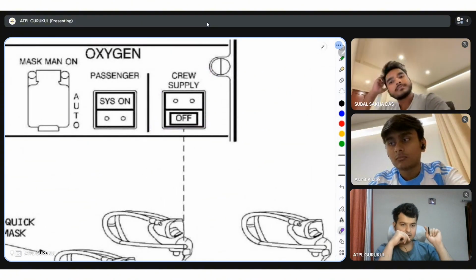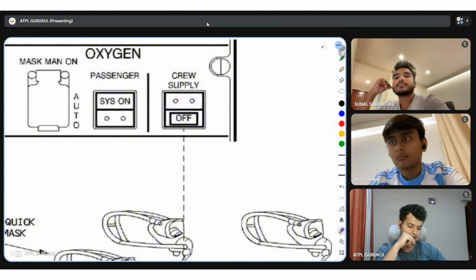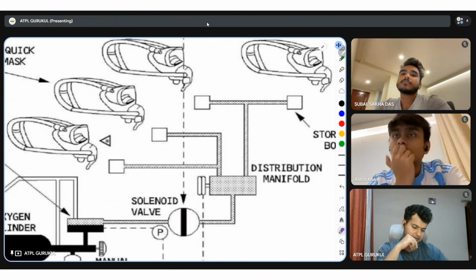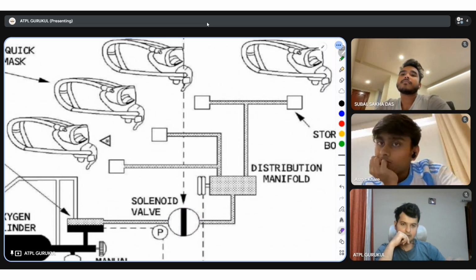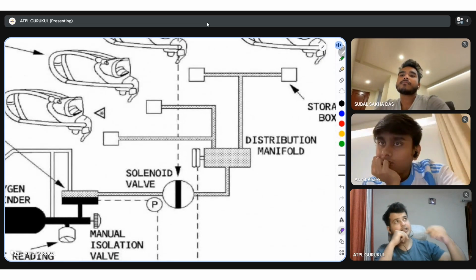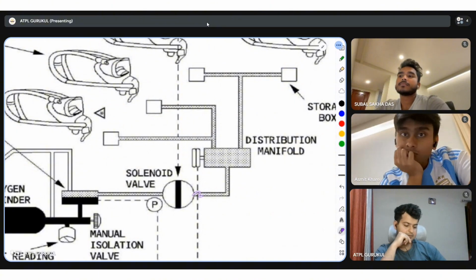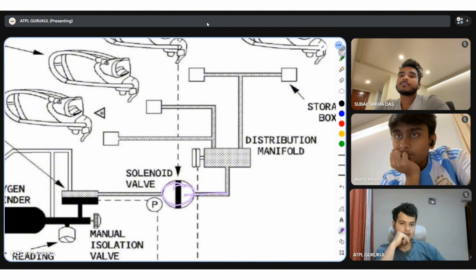When you press it, the OFF light comes on below. You press it again, this entire thing will become black and blank, and this valve will open. When you press it again, it will go off and the valve will close. But when the oxygen is being supplied, when you're in your cockpit preparation flows and you turn that button on, this particular valve will open.